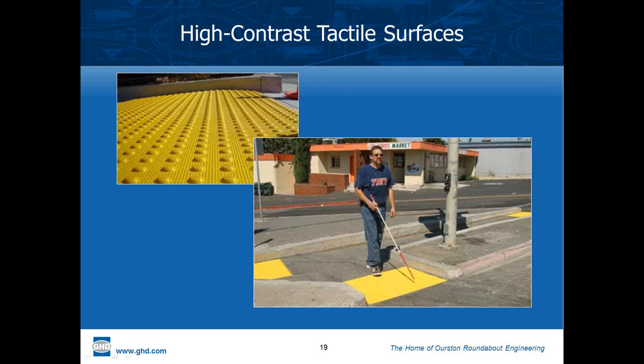As it stands, the U.S. Access Board has published some draft proposal for access of right-of-way, which is a fancy way of saying rules for crosswalk design and treatments. And at present, they have the need for traffic signals. MUTCD and some of the committees, whether it's roundabouts or traffic signals, are responding with development of new devices for audible, countdown, and pedestrian actuation. In the roundabout side of things, they're doing research on a rapid rectangular flashing beacon. I'll show you some examples of that.